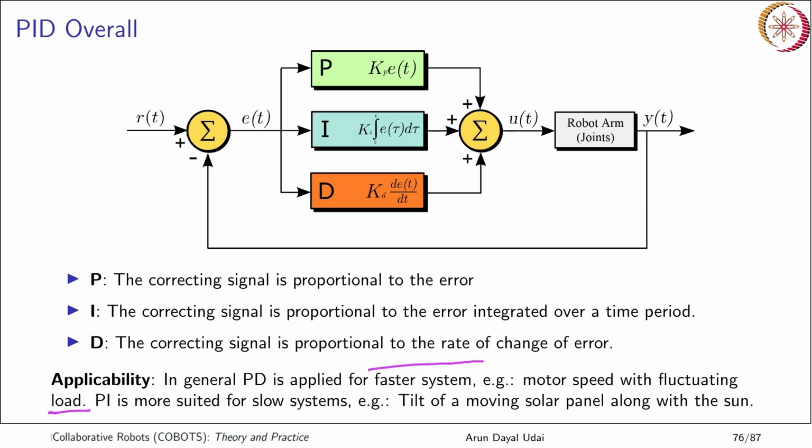That will try to slow your speed, but you want to maintain your speed in order to maintain your frequency. Changing the speed changes the frequency, and it should be 50 hertz. So your alternator normally rotates at a constant speed because you want to maintain the constant frequency.